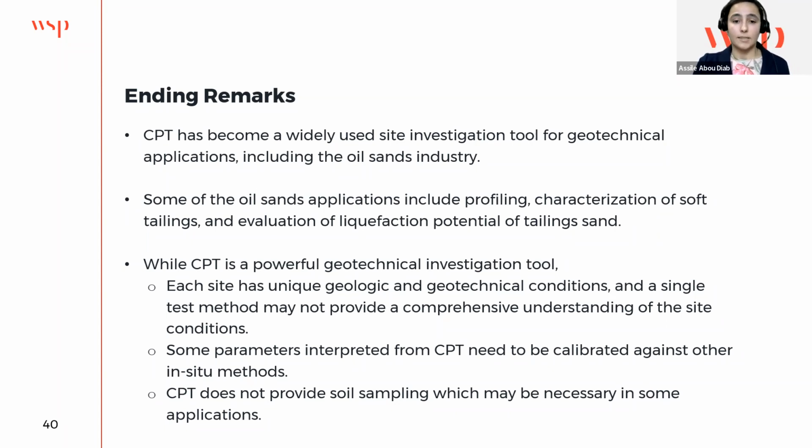And sometimes just one test method is not enough to provide a full comprehensive understanding of the site conditions. And we shouldn't forget that some parameters interpreted from CPT need to be calibrated against other in situ methods in order to represent the actual specific site conditions. And CPT does not provide soil sampling, which may be necessary in some applications.